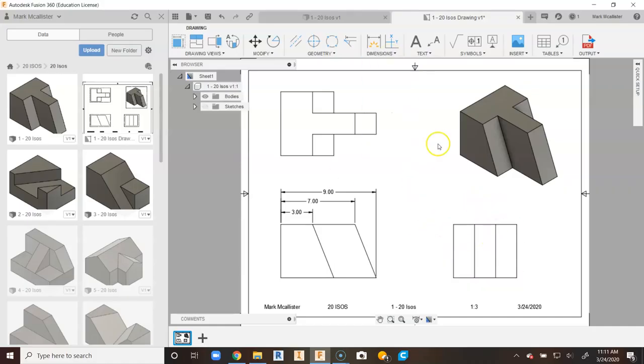Now for the depth, we're going to go ahead and use our side view, and I'm just going to click on the dimension button for this because it's also super convenient just to stay with just that dimension button. Baseline dimensioning is good if you have a lot of dimensions. We didn't have a ton of dimensions over here in our front view, so you can make a strong argument that it's just easier to use this.